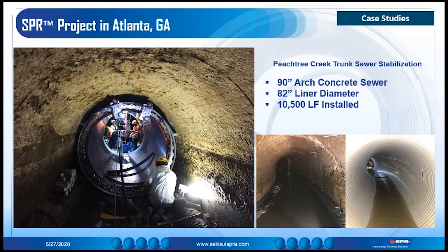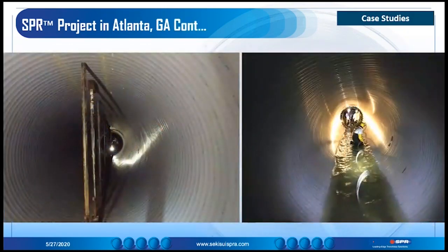During days when the bypass was not enough to safely line the pipes, the crews left the pipe, bolted the equipment in place, then returned to lining once the high flows subsided. In addition to the bends that were done on the first slides, in the second slide, you can also see the simple bracing system used during the grouting process, as well as the everyday flows during the lining. As the lining progressed towards the pumping station, Ruby Collins crews were able to complete the lining with flows up to their knees. The lining portion of this project was completed in a little over 10 months.